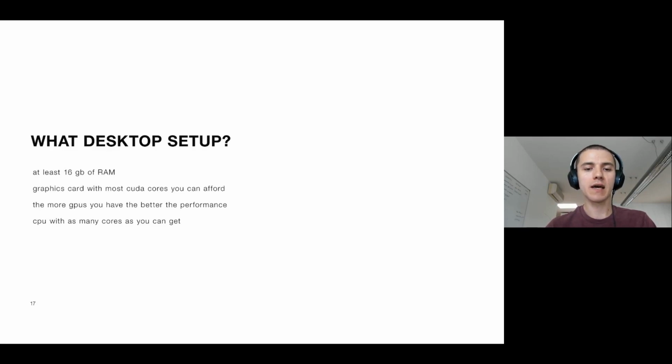Let me just add that every photogrammetry software has some kind of settings that allow you to choose the level of detail you want. In the case of Little Matterhorn, we used Reality Capture with 64 gigabytes of memory, and the whole process worked really flawlessly, I would say.